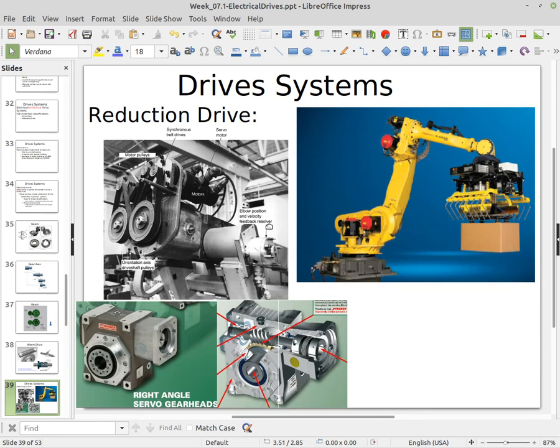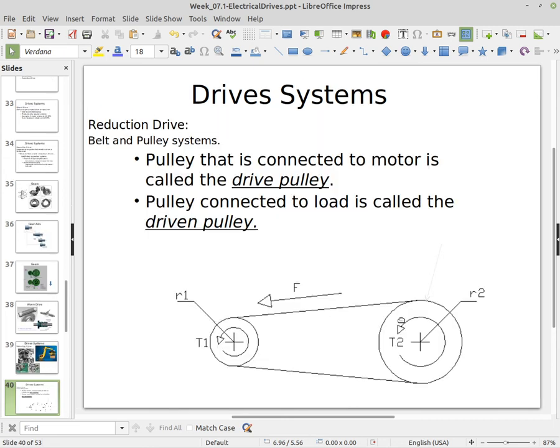All right, so when you look here, to lift very large loads, we need these reduction drive systems, because we're trading the speed. Electric motors can run very fast, much faster than we really need most of the time for automation needs. So we can make the motor smaller and then basically trade that speed for torque by using these various reduction drives.